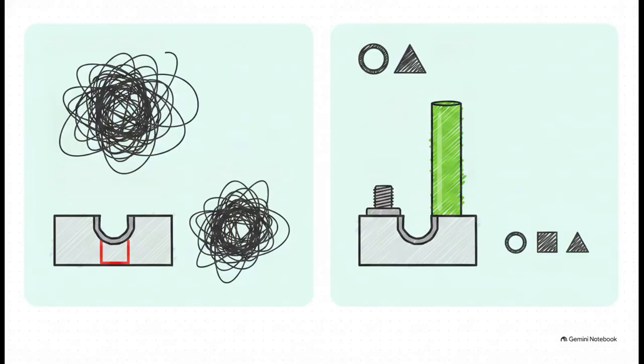Think about what this means for you. If you're an engineer designing a stacked assembly, and you try to calculate your virtual condition using just the standard formula, maximum material condition minus position tolerance, without accounting for that projection height, your math is going to be dangerously wrong right at the mating plane. The projected zone is what ensures your virtual condition calculation actually reflects the real physics of the fastener hanging out there in space rather than just the empty hole sitting in the block.